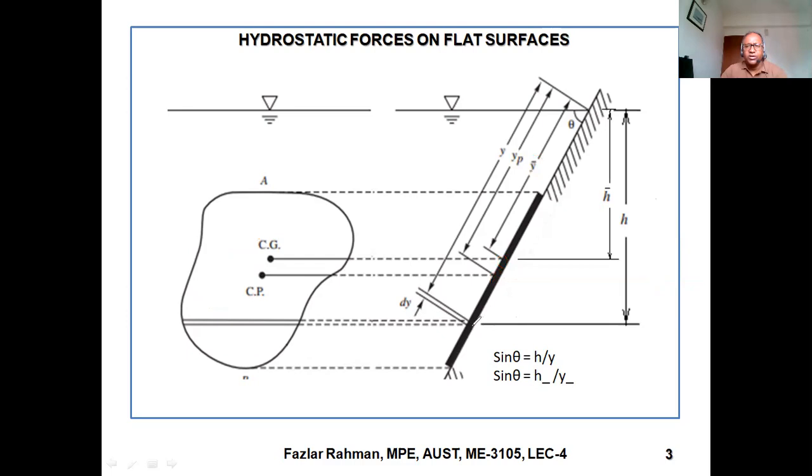Okay, now this small strip is dy. Vertical height is h. You see, if I make vertical height, then right at the bottom we are saying h. What will be the height over here? Less than h. But we are considering the area extremely narrow, dy, a small segment. So we are not considering that difference. Okay. So how much will the fluid pressure be in that small segment?